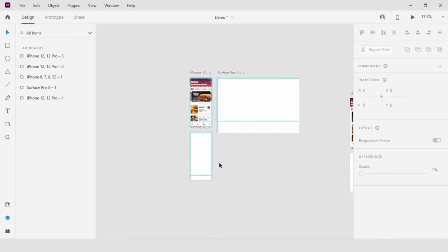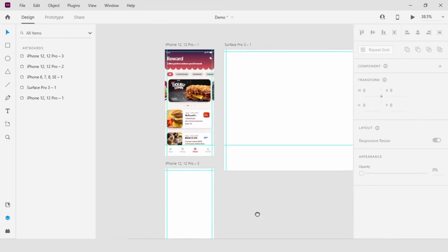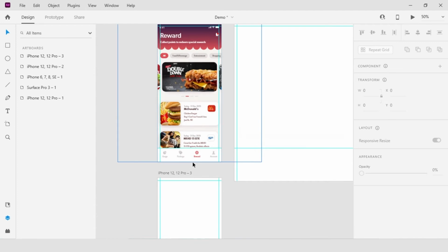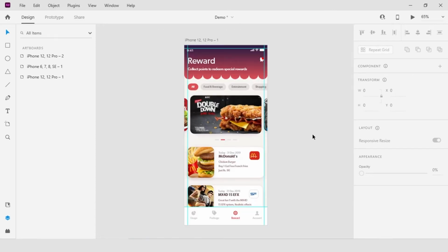When I zoom in a little more tightly, I get those indicators. The idea was that you wouldn't be able to really see where you are dragging at such a small percentage, so they suppress the visibility of those guides in that situation. Grids are applied at a global level when you are designing for your site. You can set the global attribute as the default and then override those defaults as you go along.